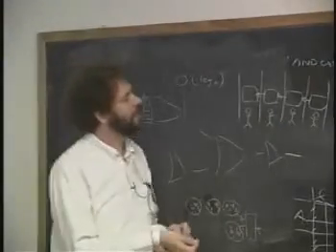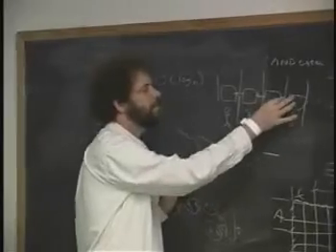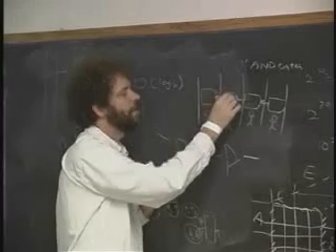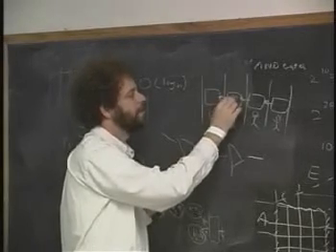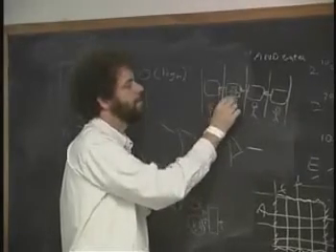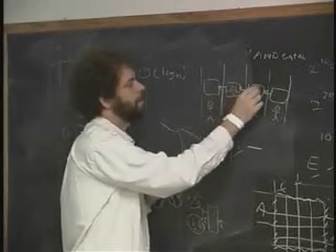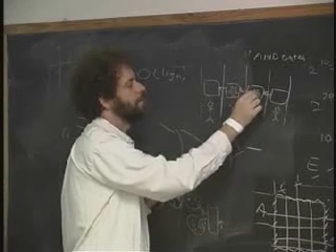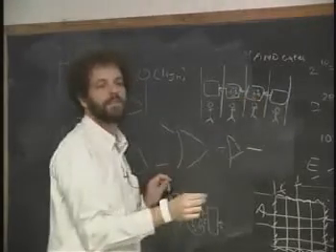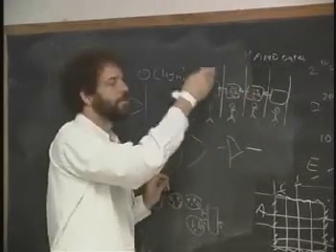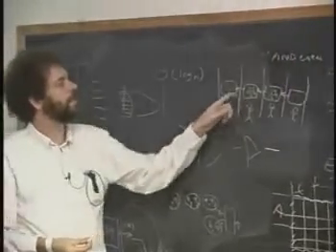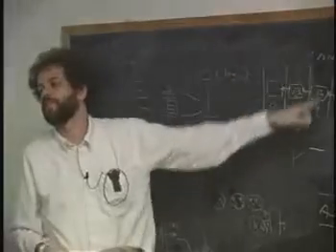And the idea here is that the add for a given number proceeds through the line in stages. And while one add is having bit number 20 done, so here's A plus B, and it's the add number K. The next one is having bit number 19 done, and that's A plus B, but it's a different A and a different B, and it's number L. Okay, and so each one of them is going to march through. And so we will pipeline. The same total amount of work is done, but notice that these guys don't have to wait until the entire line is finished before the next one gets put in.